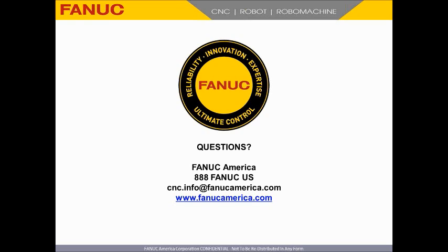Here's another question from the audience. Can the probing cycle movement profiles be edited, or are the movement profiles preset? Oh, no, it does what it does. Within the cycle itself, you really can't get in and mess with that. But I mentioned where it goes down and does a double touch, right?